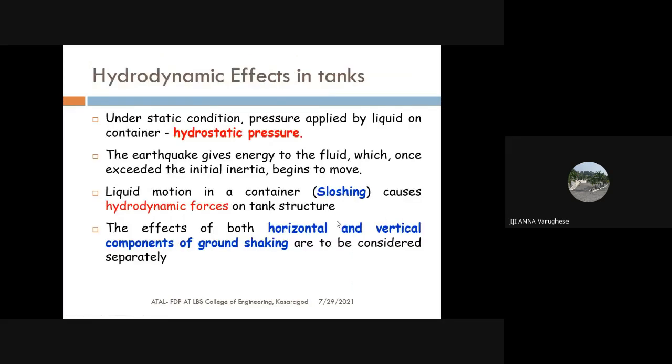Now, in order to incorporate the hydrodynamic effect due to the moving water inside the water tank during earthquake excitation, we should consider both hydrostatic pressure as well as hydrodynamic pressure. And you had already seen the variation of hydrostatic pressure, which is acting on the side wall. It is triangular in shape, and the hydrostatic pressure acting on the base slab will be uniformly distributed.